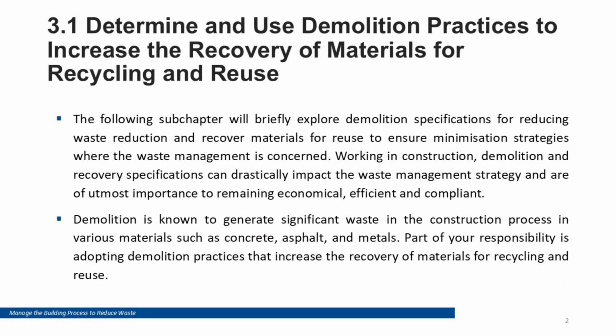Demolition can create large waste volumes, so the goal is to maximize recovery. Plan demolition to separate materials such as metals, concrete, masonry, timber, and fixtures. Use methods that support salvage rather than mixing waste streams. Confirm any regulated materials such as asbestos are handled by licensed specialists. Good demolition planning reduces landfill, increases recycling rates, and can create cost savings through recovery and reduced disposal.